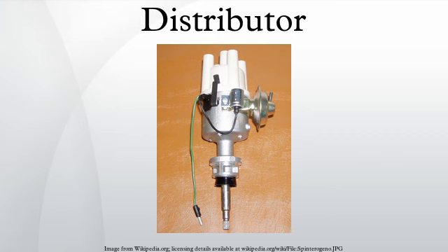Most distributor caps have the position of the number 1 cylinder's terminal molded into the plastic. By referencing a firing order diagram and knowing the direction the rotor turns, the spark plug wires can be correctly routed. Most distributor caps are designed so that they cannot be installed in the wrong position. Some older engine designs allow the cap to be installed in the wrong position by 180 degrees, however. The number 1 cylinder position on the cap should be noted before a cap is replaced.